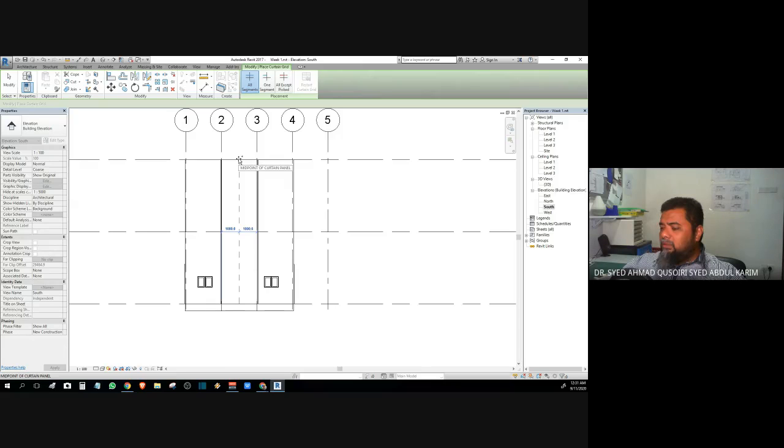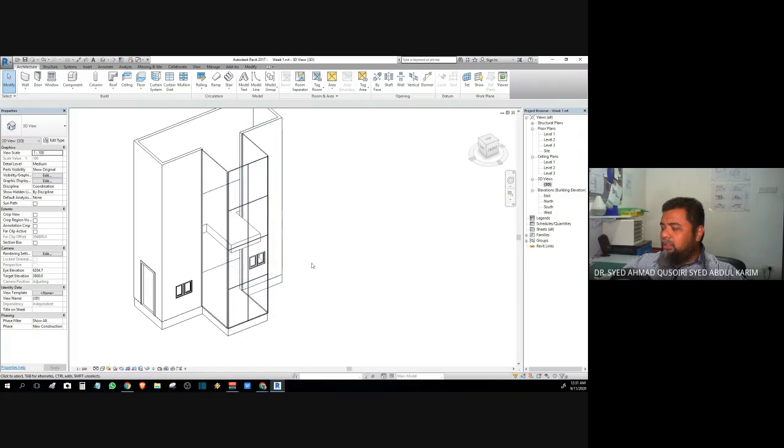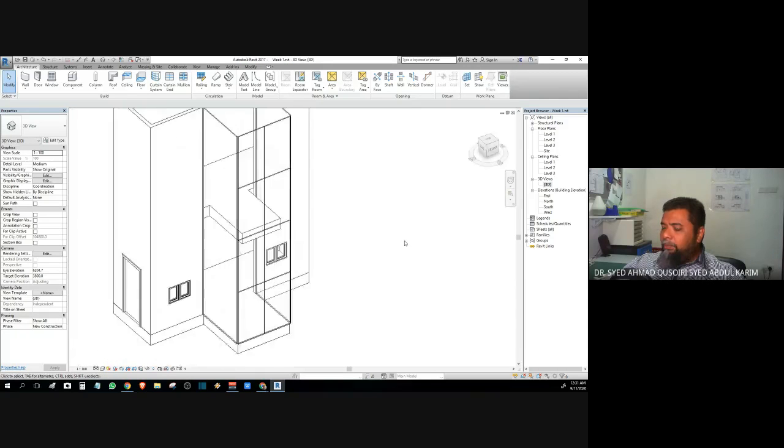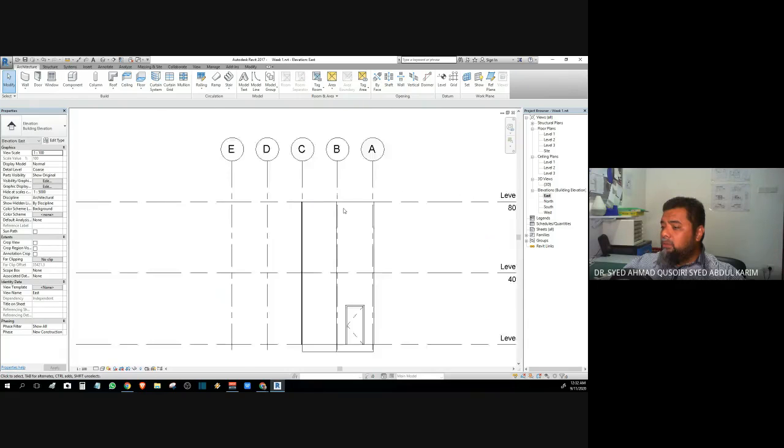Okay, so go to the edge of the glass. You can see it's written there midpoint of curtain panel. So I'll click here. So that's my first grid. And then I'll put center here. Another one. Okay, so that's the second, and I'll put it here, and I'll put it here. Okay, so if you check the 3D, we have an 8-panel glass at this space. So I'll be repeating that at all the bases of the curtain wall.